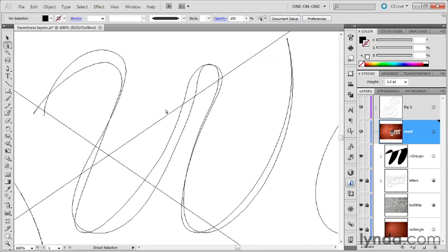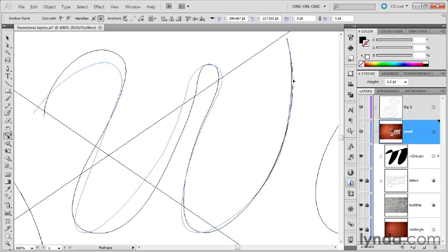click somewhere inside of the illustration to deselect the path, then click on one of the segments to reselect it. You don't want any of the anchor points to be selected, however. Then we're going to go ahead and switch from the scale tool to the reshape tool, that very same tool that we used in the previous movie. And I'm going to drag these anchor points around in order to modify them relative to the rest of the